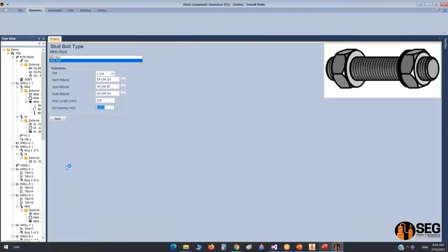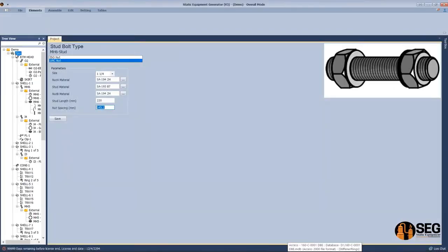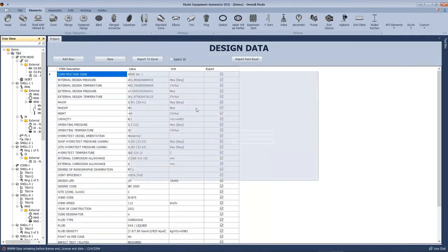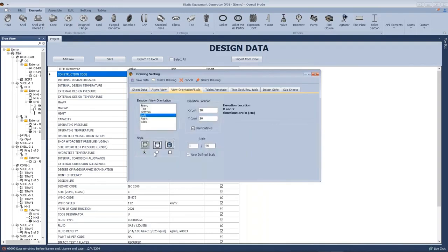During our selection here, you have the ability from the drawing. If we right click and from the drawing right here, if you select this style, that's shaded style or hidden lines. So in this type, all hidden lines on the drawing will be visible. But if you select this style, no hidden lines. And this style makes the vessel shaded, taking the real color on the 3D model.